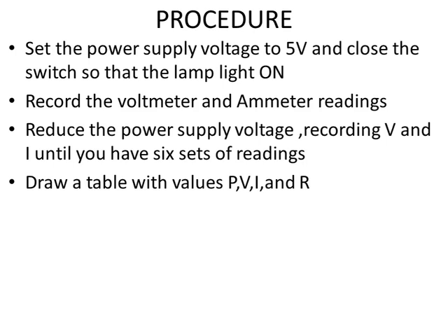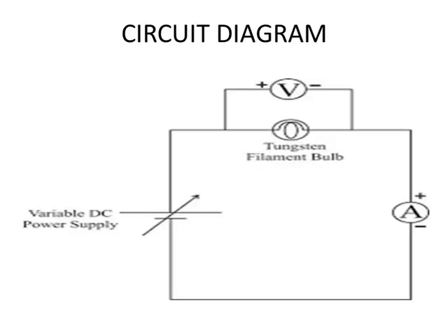P, I, and V. Remember I said that you get values for your P, which is a variable power supply. You will have recorded your voltage, the current, then you get your resistance. You can get resistance since we're having values for V and I, so you'll be able to get your R from Ohm's law.